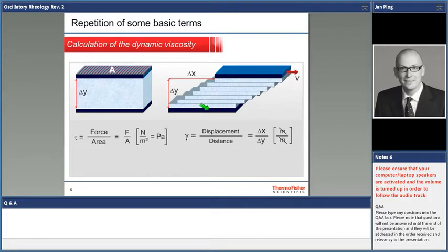It is 0 at the stationary plate, and thus for steady shear flow experiments, we need to find another parameter that describes just the dynamic state of the whole fluid, and that parameter is the shear rate. For those of you that might be familiar with it, the shear rate is nothing else but the deformation or speed gradient in this flow field.